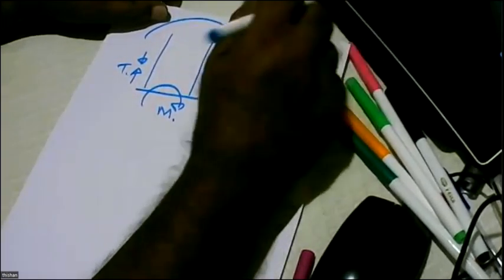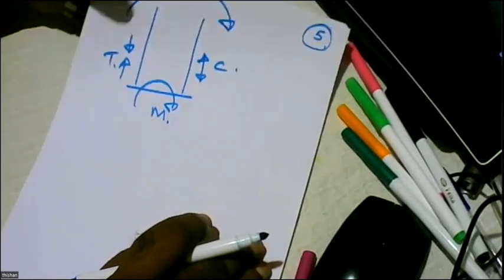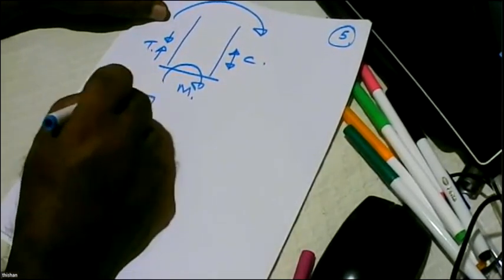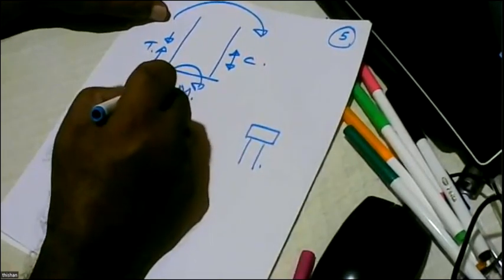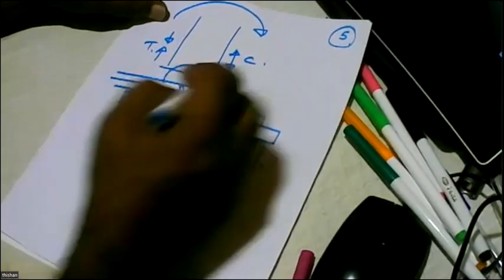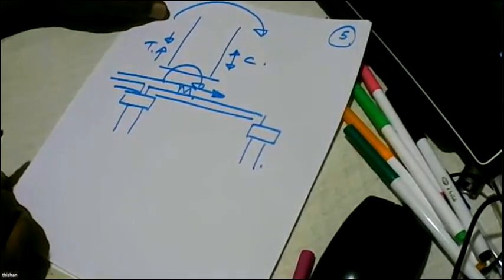So there are easy calculations that you can perform. So if you have a computer model, you can get a good idea about the behavior, because sometimes what happens is, you will find that the pier is like this, the other pier is like this, and you are going to place one beam. Now another beam is placed here. Sometimes the next beam might be brought on top of this beam that has already been placed, because you have to erect some rails and transport the other beams.